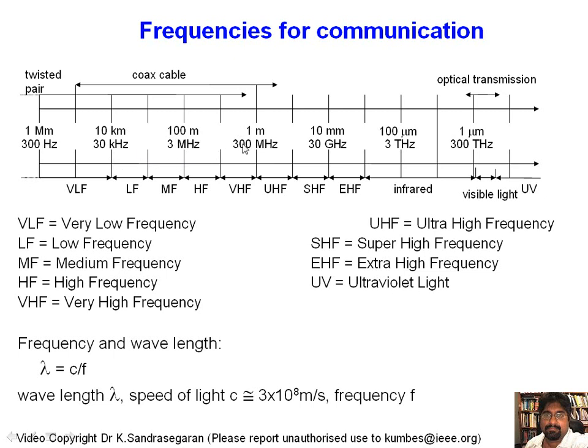Okay, so when we are looking at something of the order of gigahertz, the wavelength, remember there's a relationship between wavelength and frequency, which you might have done in high school physics. They're related by this expression here. Wavelength is the velocity of light divided by the frequency. So as we go higher and higher into higher frequency bands, the wavelength gets smaller and smaller.